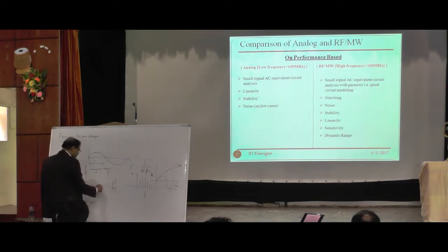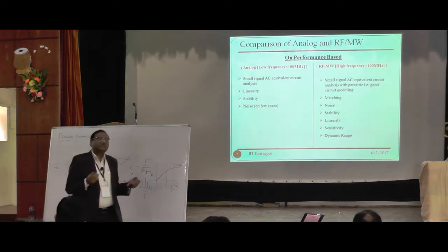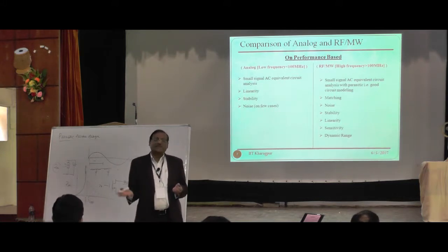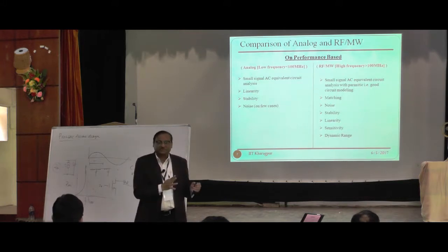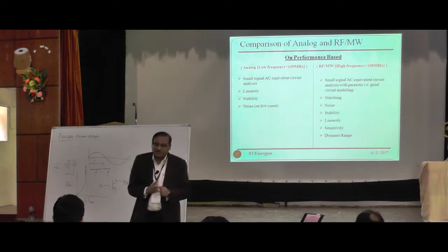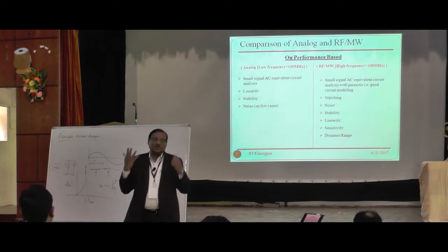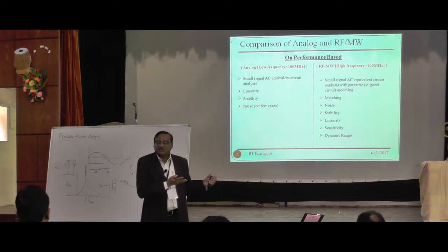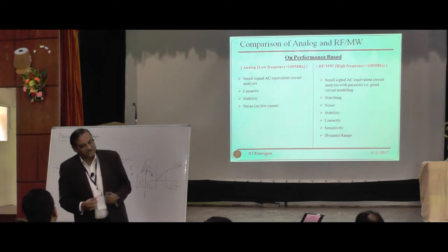This is my input and I am getting the output. Now what is an oscillation? Oscillation means a fraction of the output is fed back to the input and added constructively, not destructively. Then at certain conditions, called the Barkhausen criteria, the system itself starts oscillating without requirement of external signals.